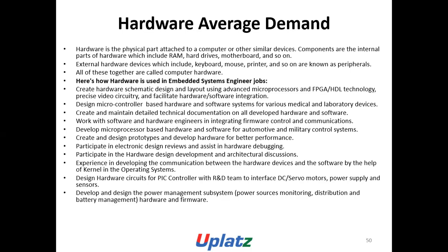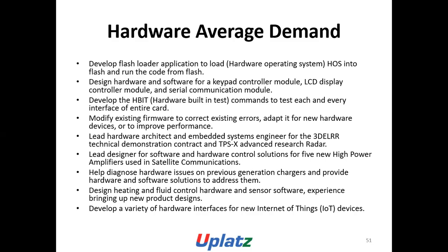Develop and design the power management subsystems, power source monitoring, distribution, and battery management hardware and firmware. Develop flash loader application to load hardware operating system RTOS into flash and run the code from flash. Design hardware and software for keyboard controller module, LCD display controller module, and serial communication module.